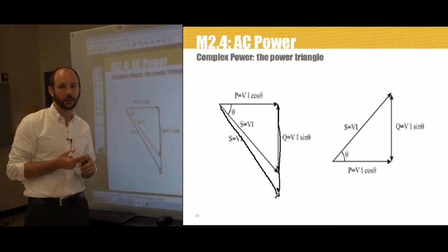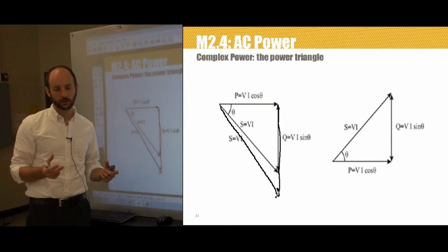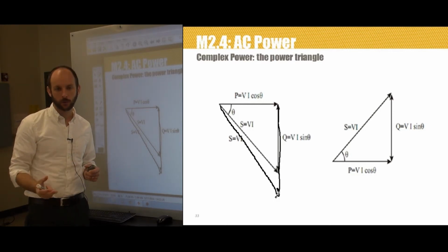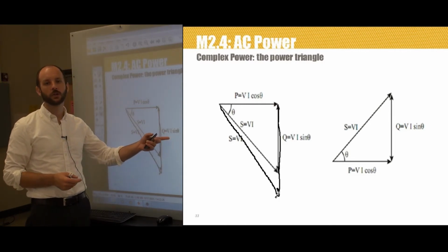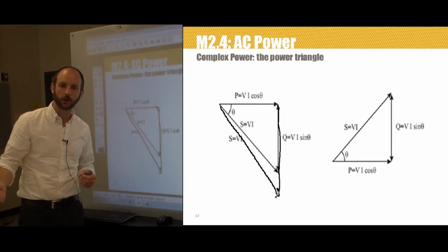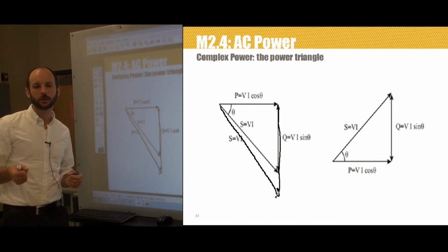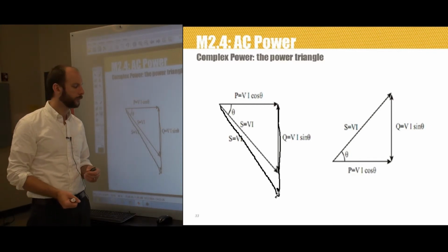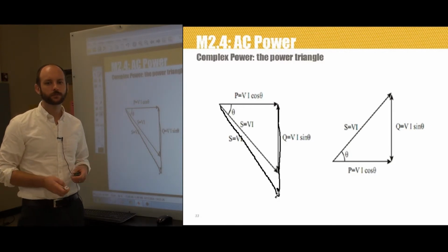And what happens then is that the physical system sees more current flow. Bigger conductors are necessary, bigger transformers are necessary, all that thing. So there are real consequences of this. Even though we're not using up energy, more current flows, and then we actually do end up using more energy because our transmission lines burn up more energy in the form of heat. A very interesting kind of cascading effect.